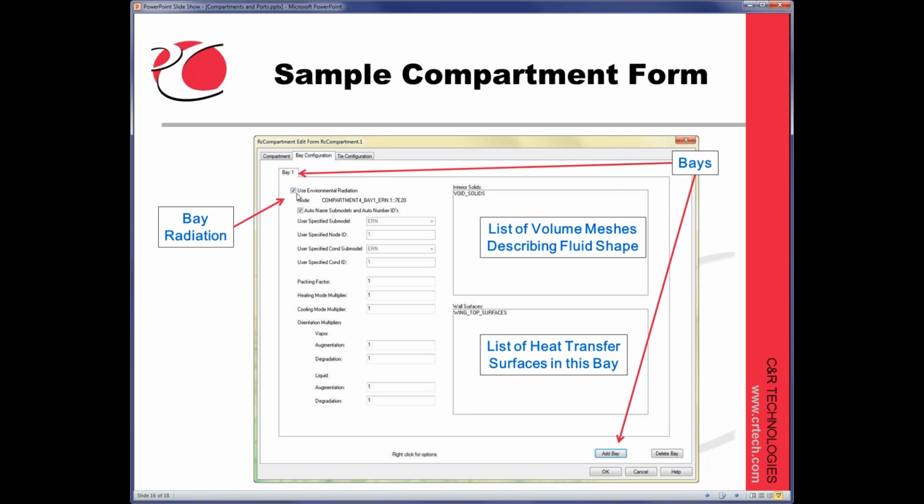There's also radiation. I haven't mentioned this, but there's actually a fast solving radiation solution that can march in lockstep with your liquid level. The purpose of this is if you have a cryogenic application, or even, we've had people that didn't have cryogenic applications that just had a very hot temperature or were very sensitive to heat leaks at the top, you can actually include simplified radiation as part of the solution.